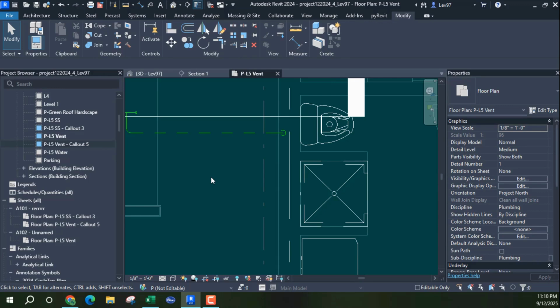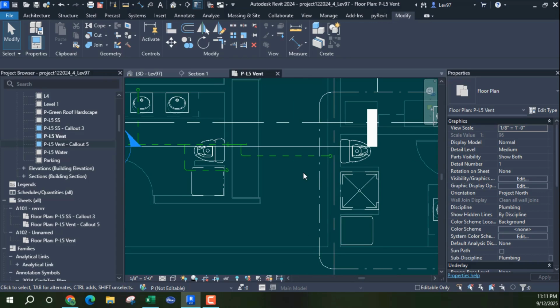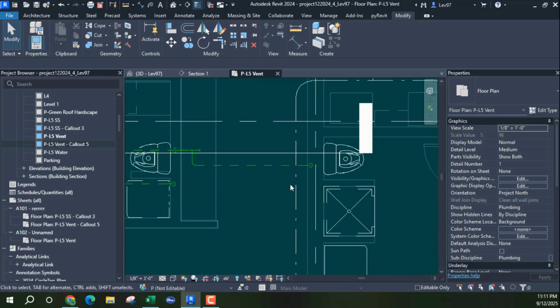Because as far as plumbing is concerned, you connect those so you can keep track of the plumbing fixture units. And it's unmanageable. Fixture units in Revit is unmanageable because you could have 500 fittings, and if one fitting breaks, the entire system goes and loses its fixture unit counts.